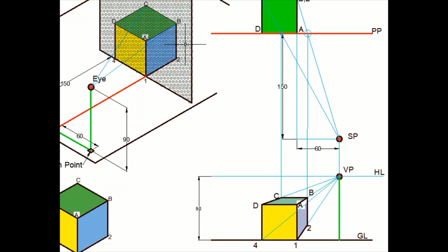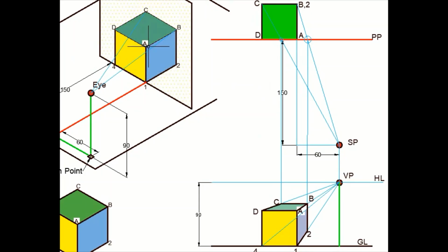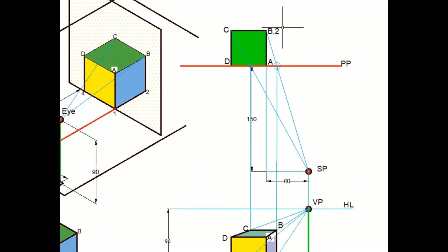Now we can also make out one thing from this example, that is if this cube or this object has this edge AB longer in size, that is face BC32 is far away from the picture plane somehow. If this dimension is even more than 50 mm, then that will actually be pushing this face BC32 in the top view on this side.